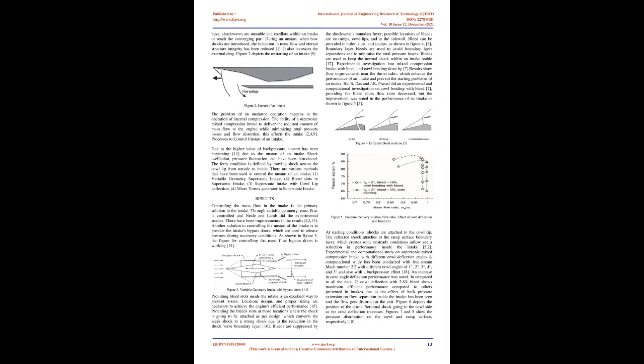The intake's unstart could occur for several reasons, e.g., overcontraction, the variation of flight conditions, perturbations in combustor operation, back pressure, angle of attack, etc. Due to a combined effect of these factors, the presence of flow-induced separation in the internal duct could also lead to unstart of the intake, generally termed soft unstart.